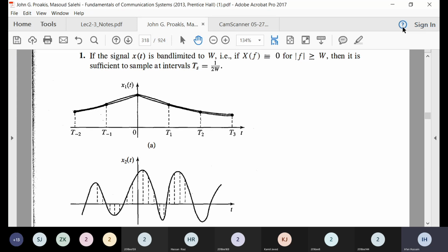All right, so this is a slowly varying signal. If I want to sample, you just take the values of the signal at fixed times. Intuitively, you can see here that I can have large sample intervals because the signal is not changing drastically. But here I will need small sampling intervals, so that I can capture the fast varying time domain signal.